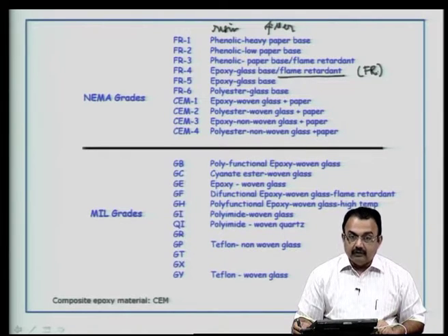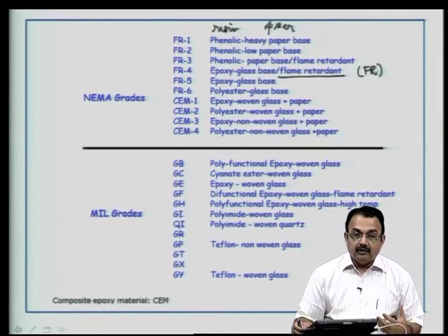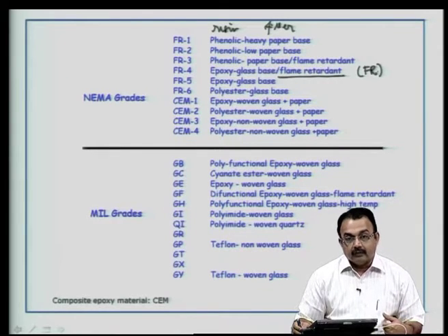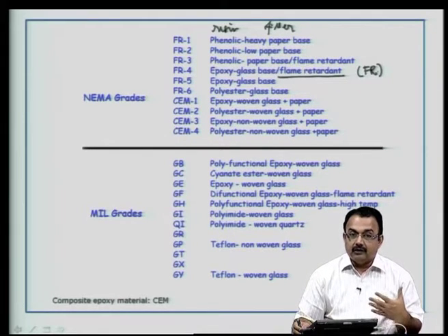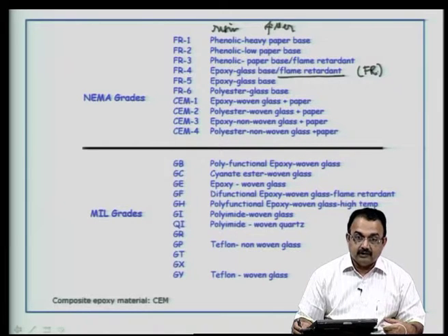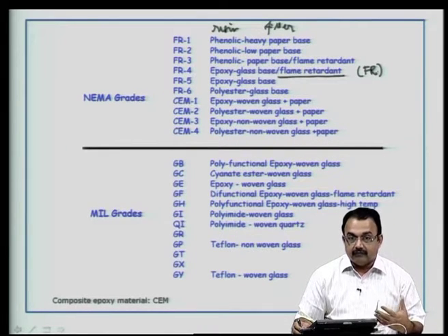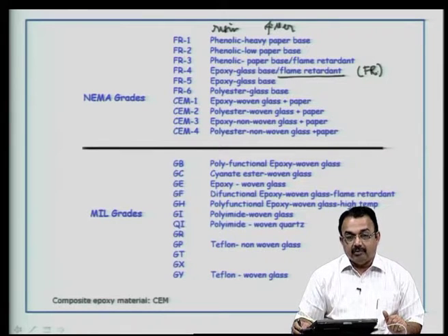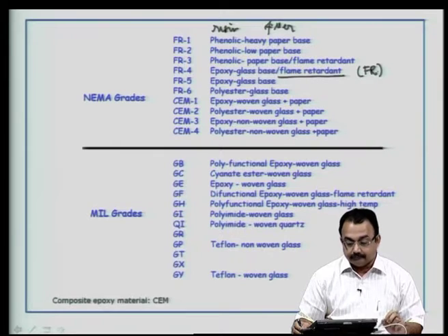So, when an equipment uses a PCB with FR4 or FR5 qualification, and if there is some kind of over voltage or short circuit in the equipment, then the PCB, being organic, can catch fire, or because of the fumes that emanate when the temperatures exceed certain limits, it can catch fire. But it should have the ability to retard the flame by itself. That means it should have a self extinguishing property.